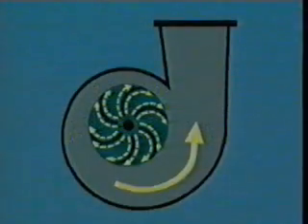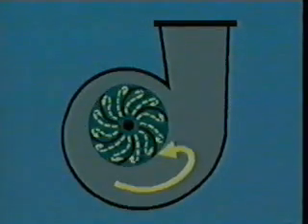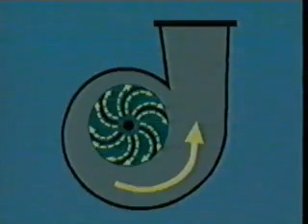At a given RPM, a decrease in flow rate normally will cause an increase in pressure. However, as the flow rate becomes too small, the gas will separate from the vane tip. As a result, that vane passage loses the ability to increase the gas pressure. When that happens, there will be a slight amount of backflow from the diffuser until lift is regained.